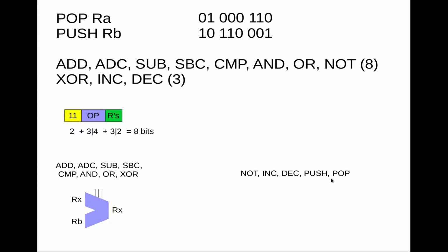In fact, the necessity of having a possibility of increasing or decreasing the stack pointer by 1 was one of my major motivations for enabling that same feature on all the registers, because we have to implement it anyway if we want to have a stack pointer. And so in this case we need to configure the ALU a little bit differently, so that the second operand isn't actually going to be the B register, but is going to be, let's say, a fixed value of 1, or depending on how we'll actually implement the decrease, it might be -1.